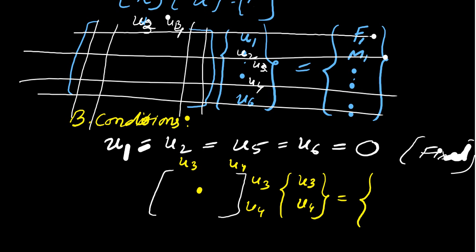So for the particular diagram, if it is a beam having UDL acting on member 2, it means for node 1 the loads become 0, 0, and the load is acting at node 2 and node 3.